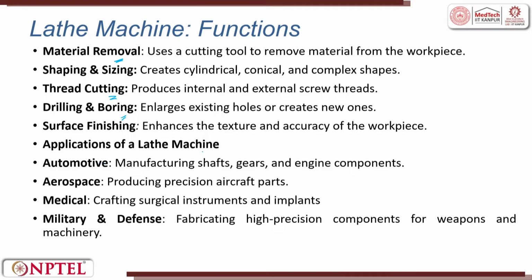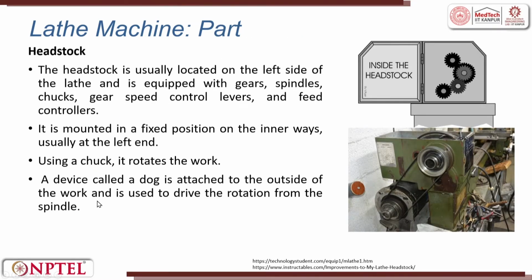And where are these lathe machines used? They are used extensively in automotive applications, in aerospace, medical and military applications. Wherever you want to develop a precision axisymmetric part, it is possible. So, let us look part by part in a little more detail. Headstock, right? You see there are gear trains.